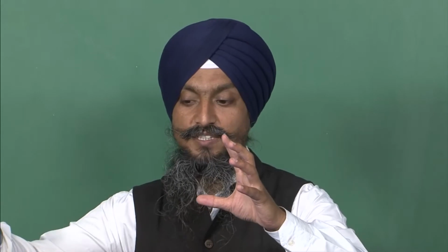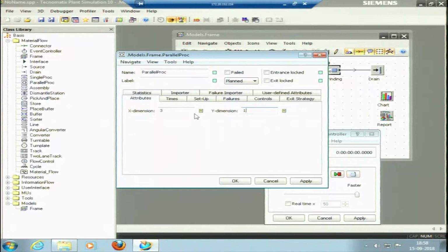It was waiting for 40% of the time. If we put 2 machines here at that successive point, now this 40% of time will reduce to 0, because now the processing is doubled here. So in that case, we can think of putting in parallel processes. When there is waiting or blocking, we can think of adding new machines, or of taking a few machines off. And if there is a lot of waiting time, sometimes we can even think of doing some other processes, like I have said in the case of the process layout.